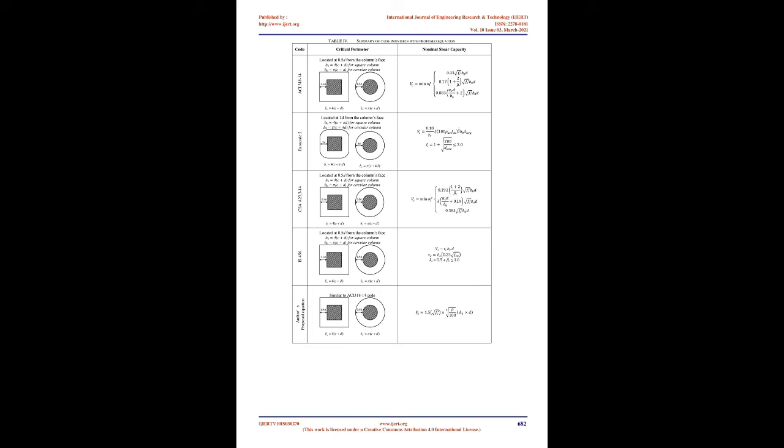The reinforcement ratios were between 0.33 to 2.62%. The effective depth ranged between 70 to 275 mm. Table 2 presents details of HSC data. A large number of normal strength concrete specimens, 243 specimens, test data are collected from literature, Susanto et al., 2018 [19], where these data are from 1956 to 2012. Table 3 presents some of the details of NSC data from 243 samples.